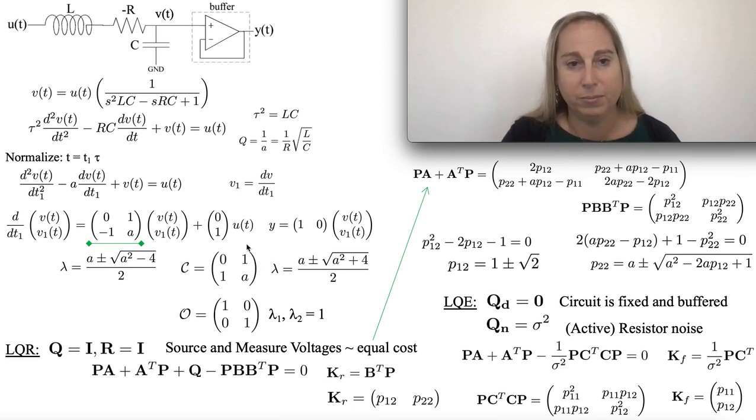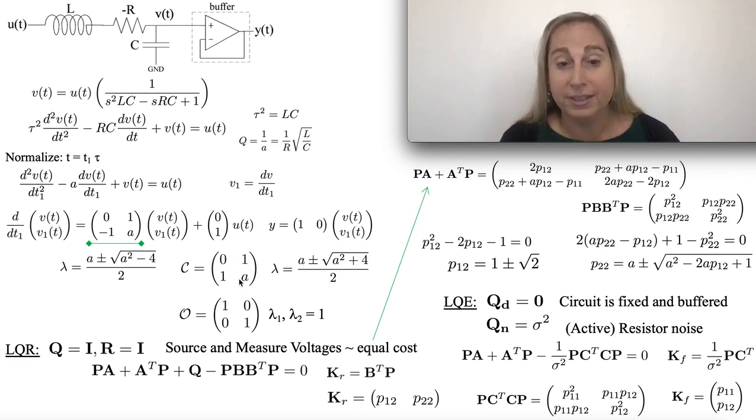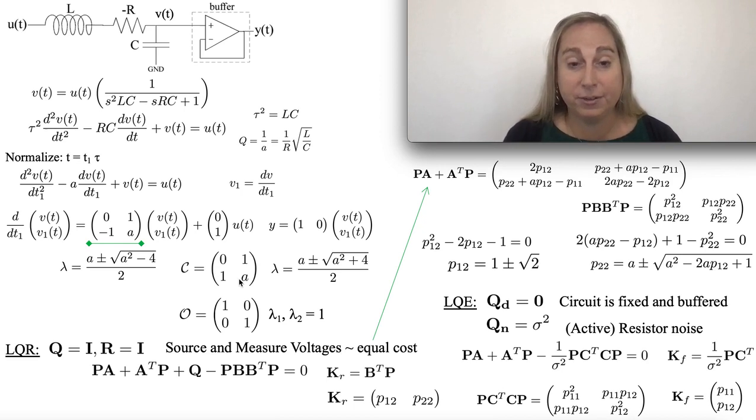Again, I know where my B matrix is, so that starts there, and then I get the extra vector for the second vector of it. It turns out this is full rank, and in fact, the eigenvalues are fairly reasonable in this case. For a different value of A, I'm probably going to get 1 plus and 1 minus. They're not going to be crazy off in magnitudes. There will be some separation there, but I should be able to get a pretty good handle on this, depending on what A would actually be in the system.